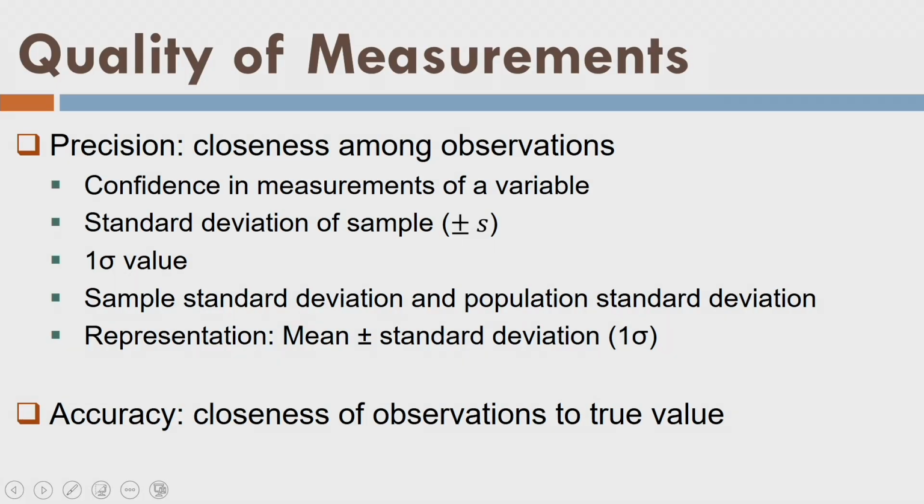So the quality of measurement is very important, and as we said, since we cannot estimate the individual true error in each observation, what will I do? I will take some estimate of the overall error, or I will have some kind of estimate for the largest possible value, so that I can always know what could be the worst possible measurement or worst quality, or the quality below which I should not think.